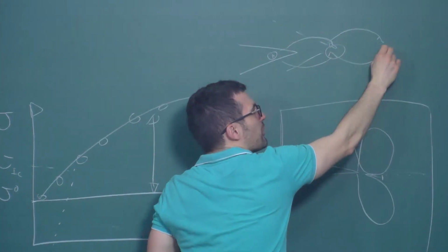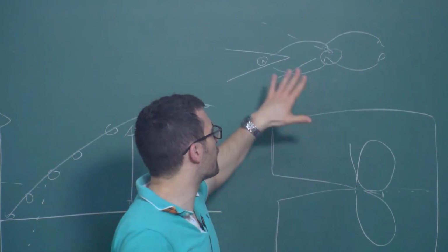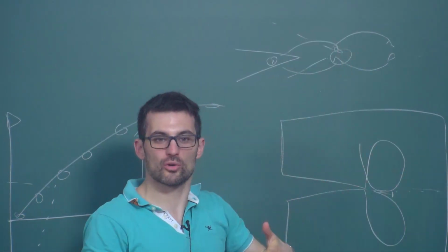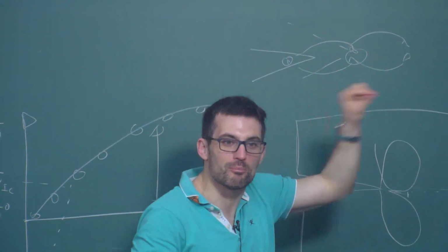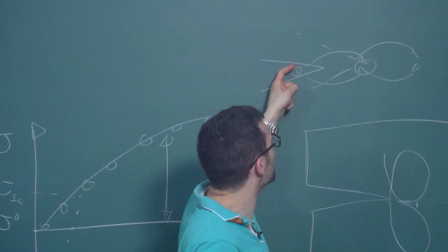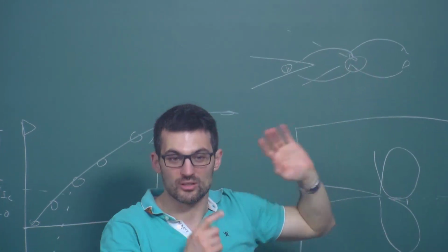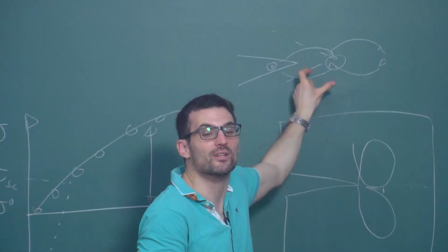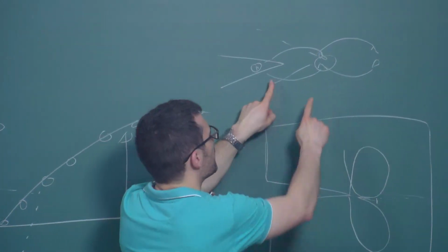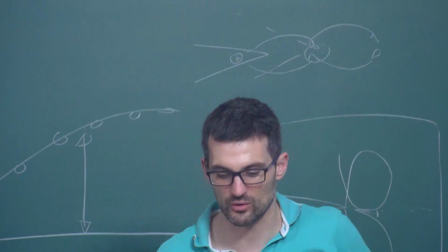The hydrogen has to go there. So even though I'm increasing my load, even though I have more stored energy, the fracture toughness that I see is quite large. I cannot grow. I need to wait for the hydrogen to go and embrittle my material. So the rate limiting step is the hydrogen being transported to this critical space. So that's good because we can use experiments to determine what is the critical distance at which hydrogen happens, and how long I have to wait.